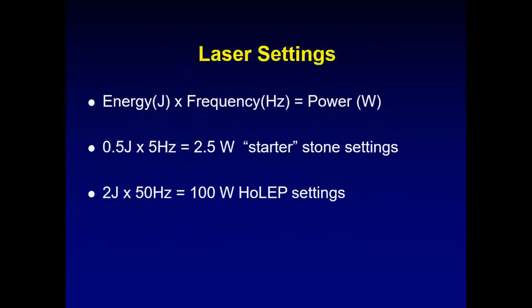So a bit about laser settings. This is very important: energy, which is in joules, into frequency, which is in hertz, equals watts. Initially the lasers which came were of 10, 20, 30 watts. Then 60 watt was the gold standard. After that, when 100 watt came, it revolutionized things. Now 120 watt has come.